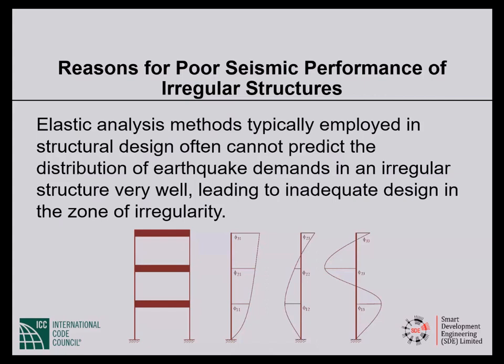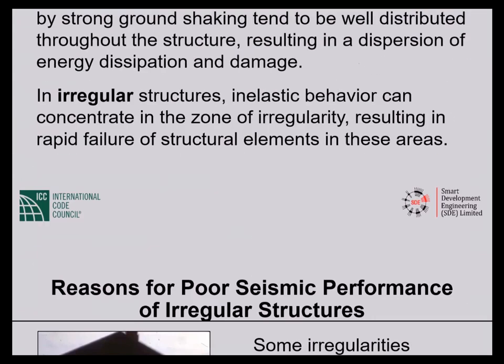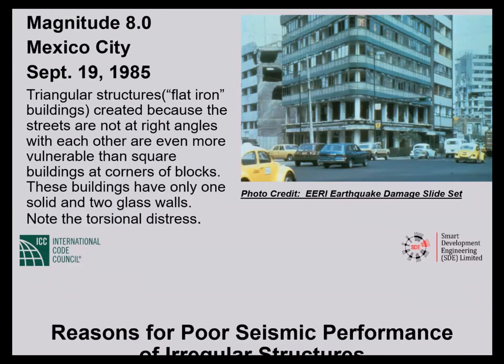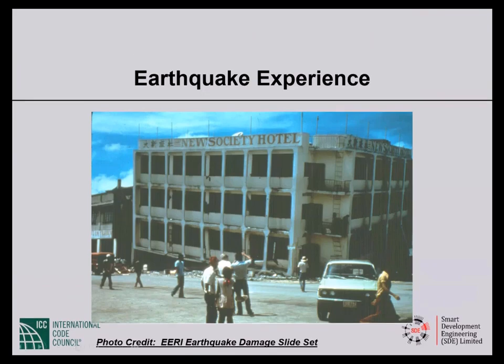Elastic analysis methods, this is very important, typically employed in structural design, often cannot predict the distribution of earthquake demands in an irregular structure very well, leading to inadequate design in the zone of irregularity. This is elastic versus inelastic. This is not static versus dynamic. And what we are saying there, I think, is maybe even common sense.